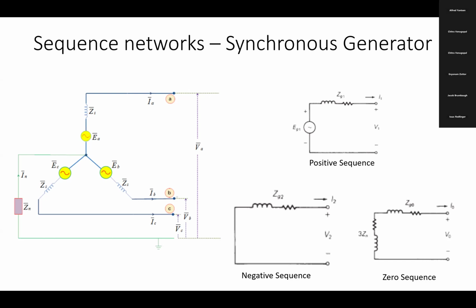The complex part comes only when you are looking at the transformer, because a transformer has two non-connected things, primary and secondary, which are mutually coupled. They are not connected. They are mutually coupled. So there is an impedance in the primary, there is an impedance in the secondary, and there is a mutual impedance between them.